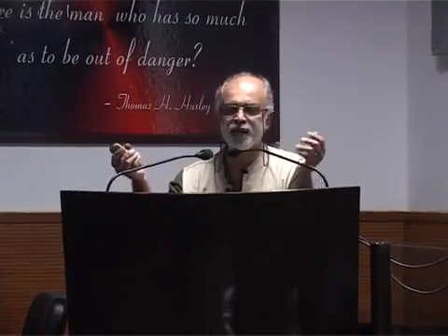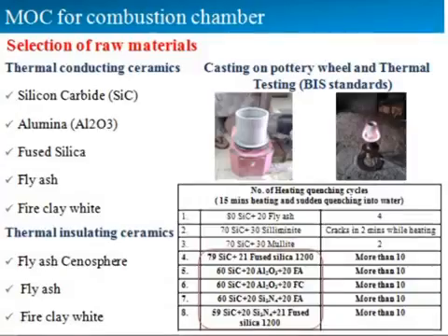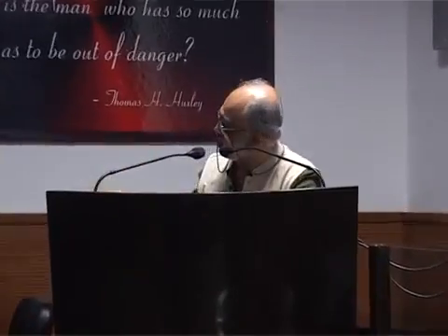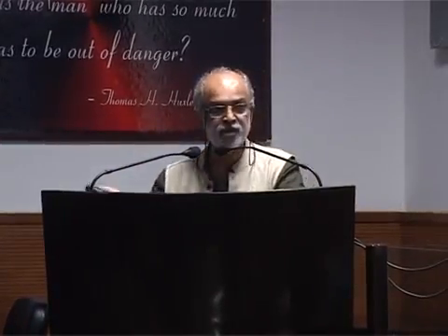So we have now developed a ceramic stove. The inside part is ceramic. There are 2 ceramic cylinders, with an inner gap which allows the secondary air to get heated up. The inner cylinder is a conducting type, the outer cylinder is an insulating type, so there is no loss of heat to the surroundings, and you are able to get efficiencies of this particular stove in the range of 55 to 60%, which is unheard of as far as any solid fuel burning stoves are concerned. Right. So these are the conclusions of the first part.